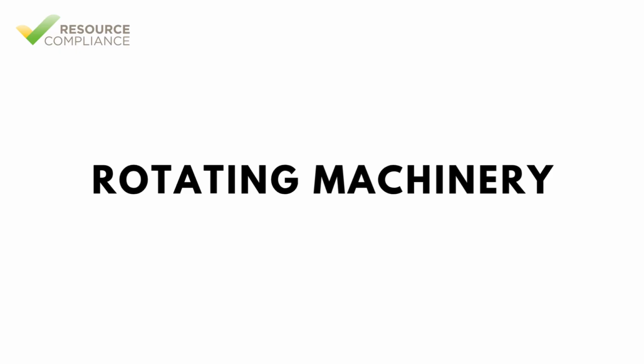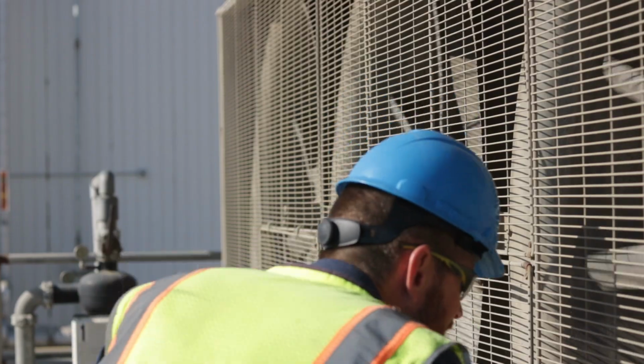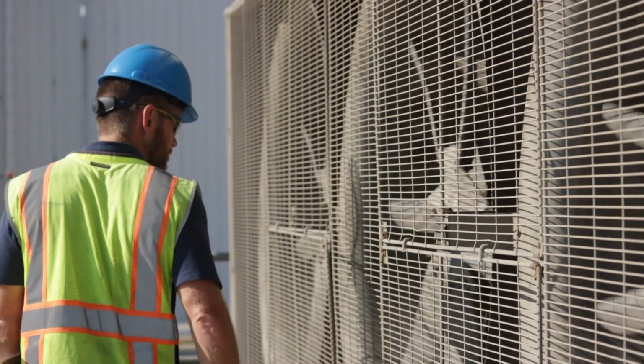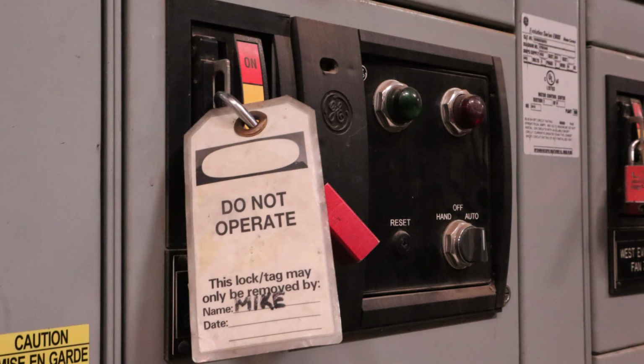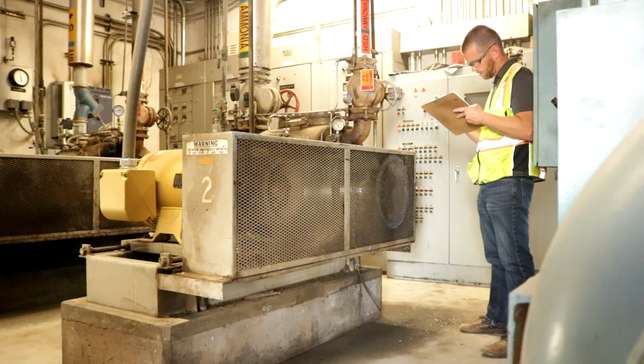Refrigeration systems contain many types of rotating machinery, including compressors, pumps, motors, and fans. These components are essential for system operation, but pose serious hazards if technicians are not properly trained. Some key safety practices for working around rotating machinery include: always isolate energy sources and verify equipment is fully stopped before performing service. Never bypass or remove machine guards while equipment is running. Guards are designed to prevent accidental contact with rotating parts.